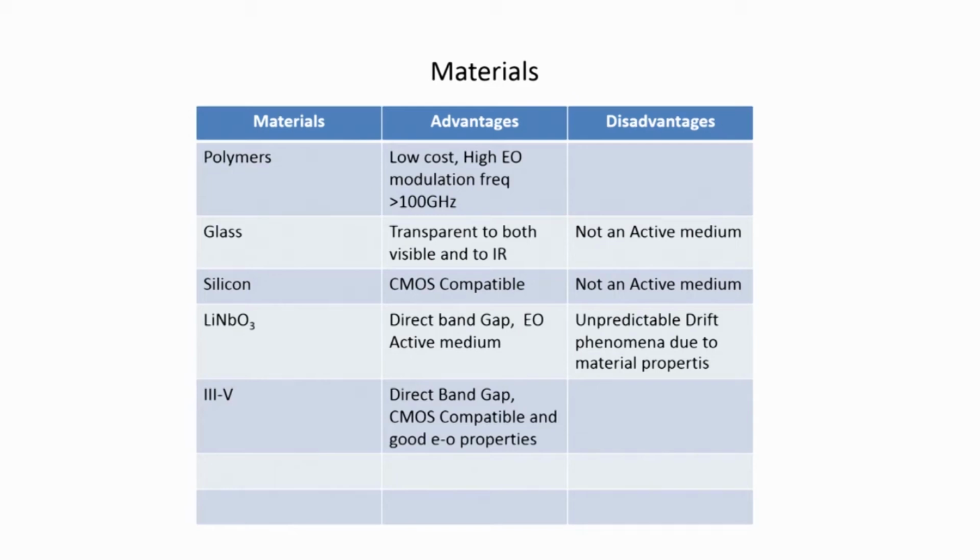You can make detectors, and more importantly, silicon has become a very important material system for MEMS applications. So, you can make a lot of mechanical devices. It has got very good mechanical properties. So, you can make mechanical devices on silicon, and of course, if you couple or combine passive photonic integrated circuits with silicon, you can make very good optical MEMS, so to say. In a future talk, we will be looking at what are called optical MEMS or MOEMS. So, this is another important reason why silicon has become important.